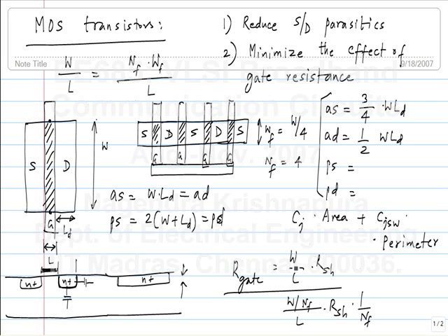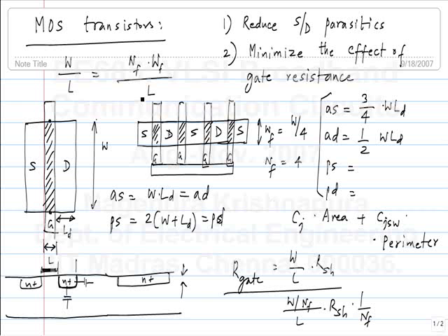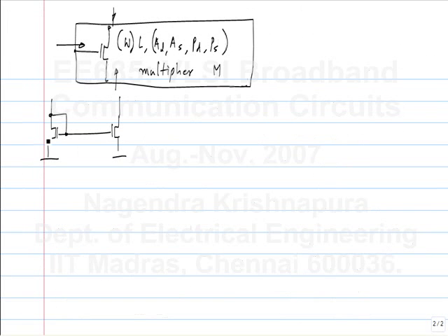So when you're doing a project or something, if you lay out stuff, you should do it in the right way. And the other aspect is about matching. So let's say you have a current mirror, and not just for a current mirror, typically whenever you have two transistors where one of the terminals is common, you can simply use a continuation of this. It's not like you have to lay out two separate units of this and then join it together. Okay. So let's say this has 2 fingers and this has 4 fingers.